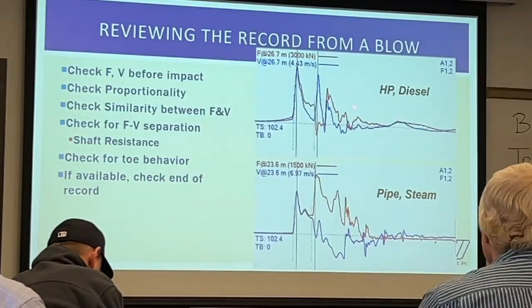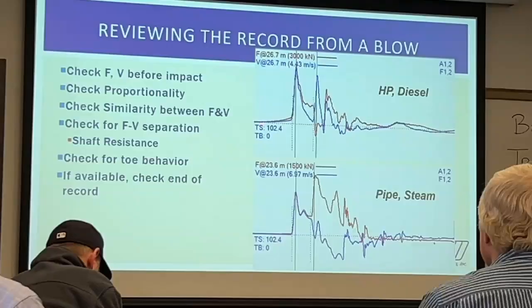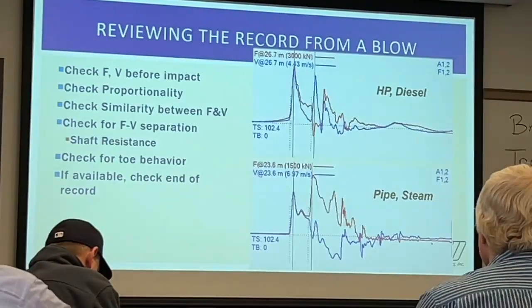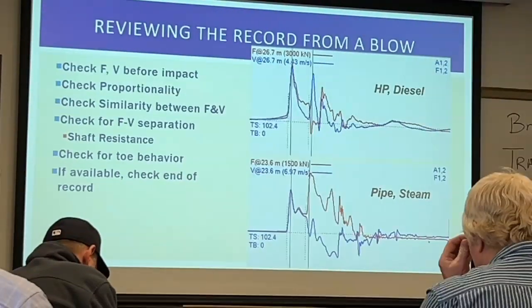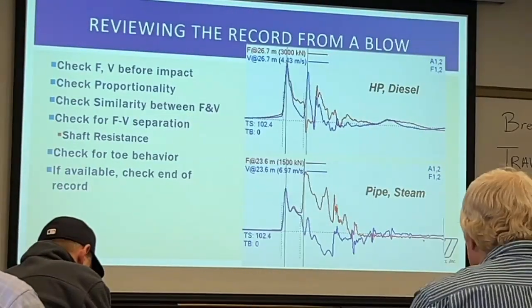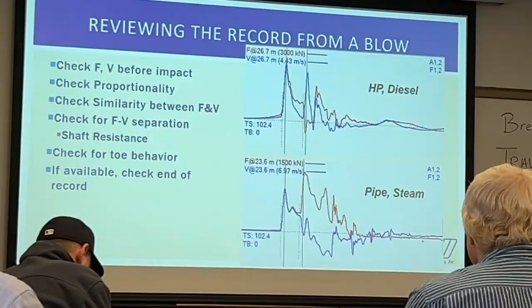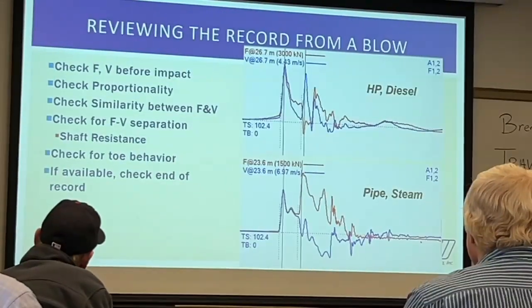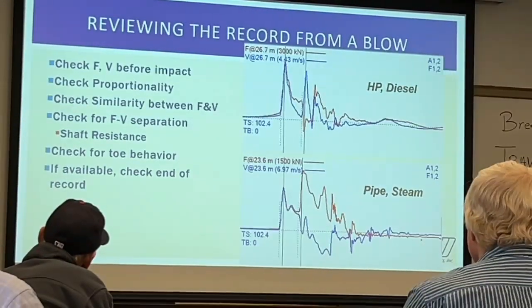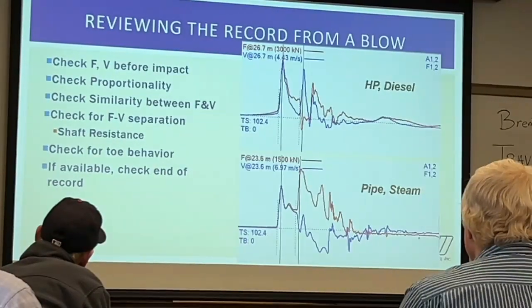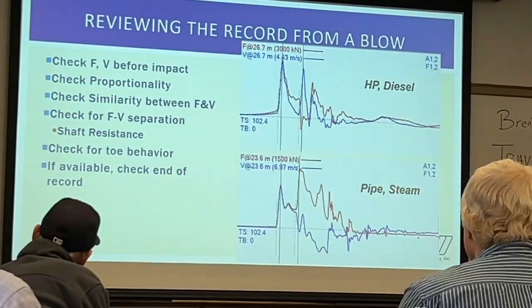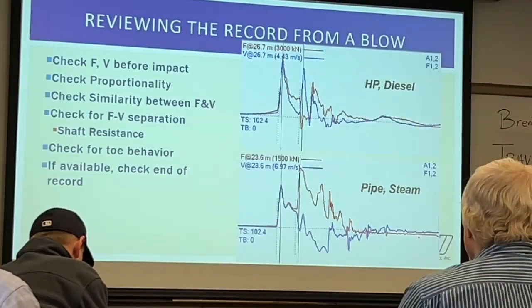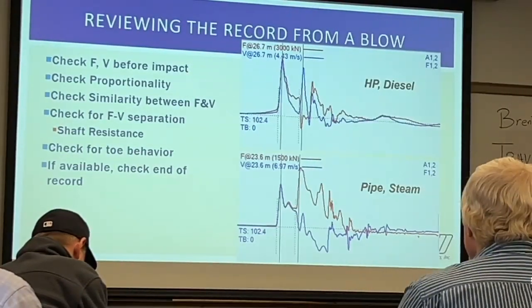And so looking at the diesel, remember Travis, in talking about wave equation, described how we model the pre-compression phase of a diesel hammer. Those ports close off, and as that ram starts to fall, the amount of air trapped inside that pre-compression chamber is fixed.